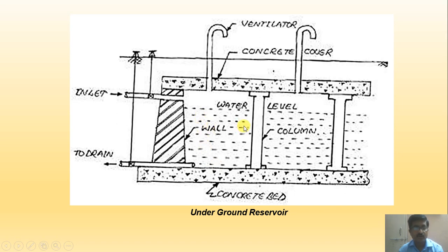Here, water pressure will act on these walls, and when it is empty, what will happen? The earth pressure will act on them. So we have to take care of this when we are designing the underground reservoirs.